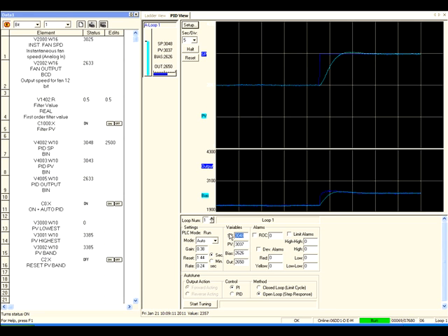Then we'll go back and set the set point back to 2048. As soon as we hit enter now, the dark blue line goes back to the 2048 value and the PV starts following that. You see a little more undershoot than you did overshoot, and then it comes back and starts settling on the set point value. This looks like a nice smooth line and a smooth graph because we're looking at the full scale of the possible value.